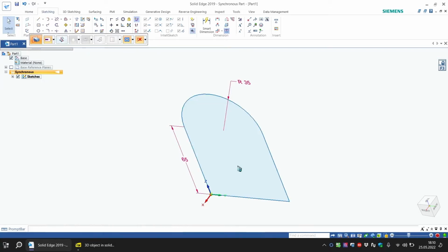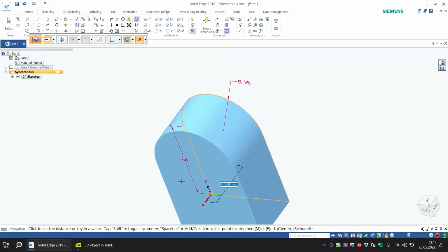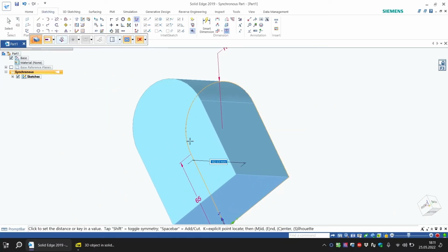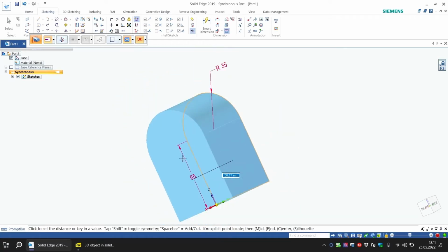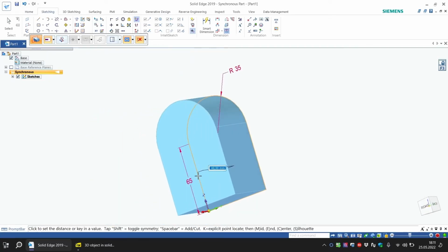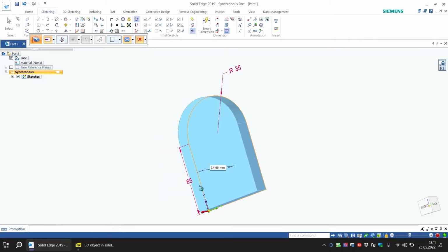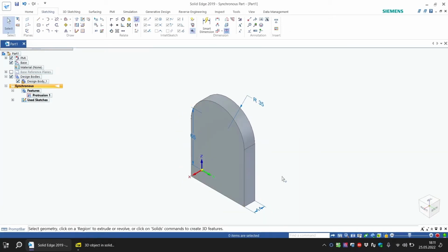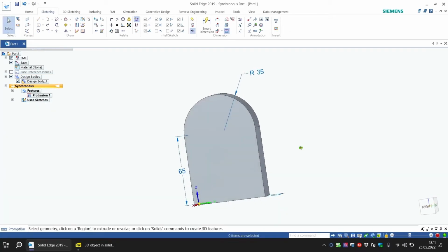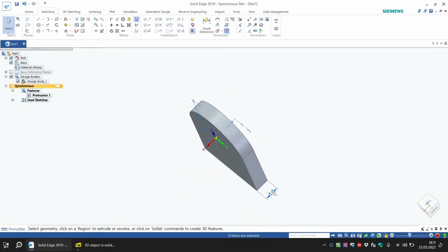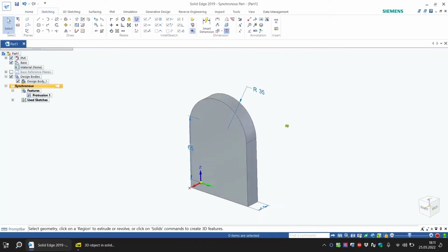So we click this one, and as you see, when I move the mouse, I'm extruding the object I created a minute ago, but I need the concrete measure of this extrusion. So I put 14 and confirm it by enter. And as you see, now we created the back plate of our object that has a precise measurement of 14 millimeters of depth.